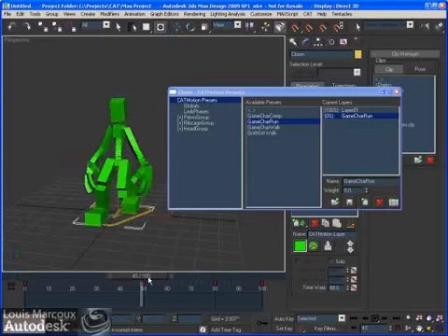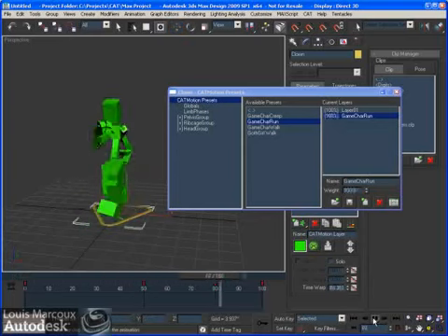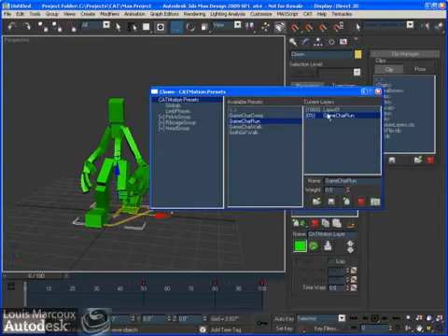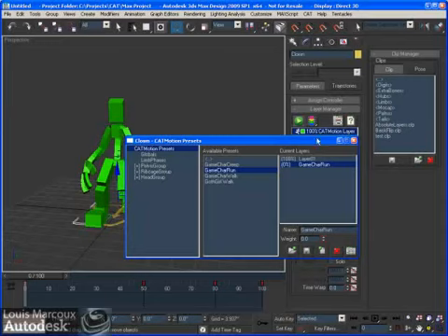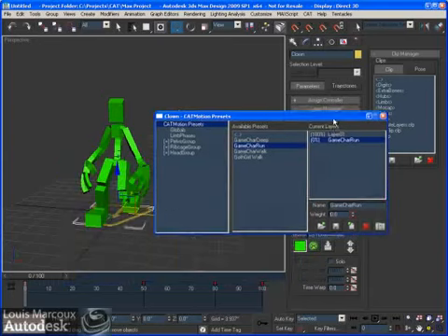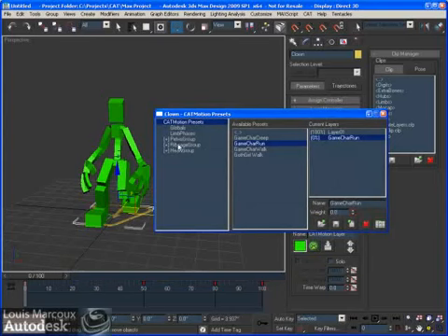And you can see that it starts running at this point here slowly and then going into running. And you can have as many layers of animation or layers of cat motion within this cat motion layer. And what you can do as well is create multiple cat motion layers and blend between all of them. The difference between blending here is that here you're blending the transformation, and here you're blending those parameters that you're setting up here. So that's the difference between the two.